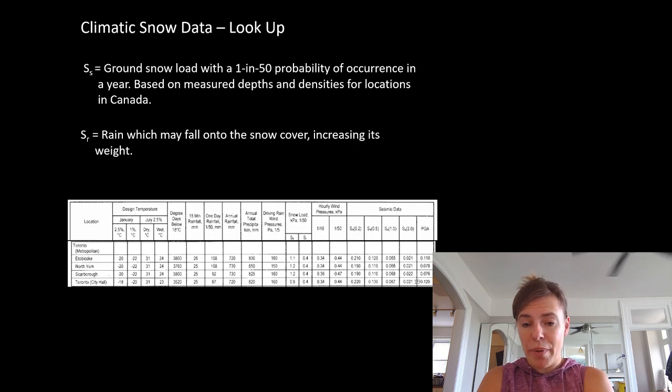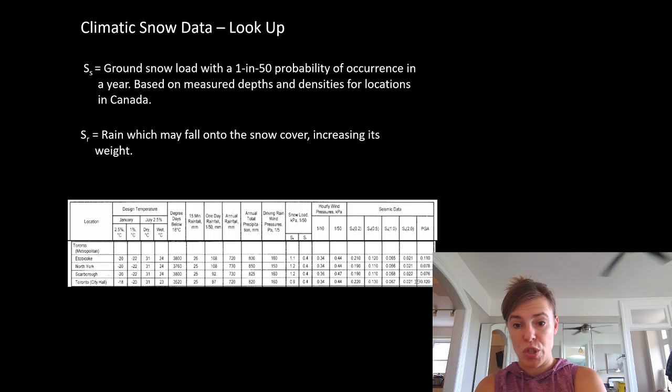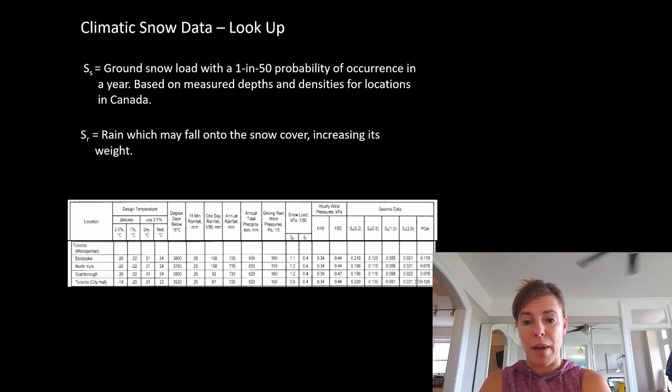That storm in 2012 dumped 127 millimeters in 2 hours. So that far and beyond exceeded the 1 in 50 year 24-hour rainfall event. We've since had other ones that are pretty darn close. It wouldn't surprise me in the next iteration of the code if some of these numbers change due to climatic changes that we're seeing across the world.